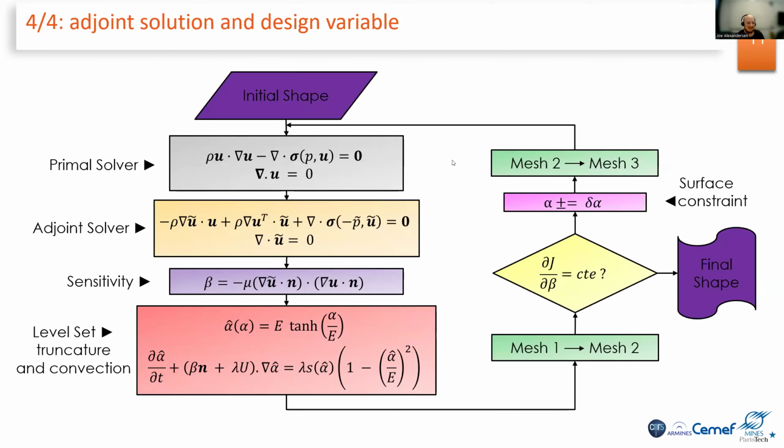And there is another strong issue. I found out later when I discussed with people that the fact that we solve U and P in a mixed formulation is more important than solving U alone, then P, and then correcting the velocity. So we are using a mixed formulation, U and P in the same matrix. For the preconditioning of this matrix, when having a high viscosity in one region and a low one in another region, it helps. And behind the linear algebra, we use PETSc for the resolution.